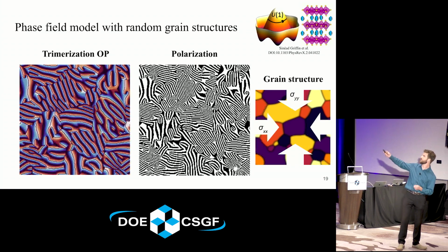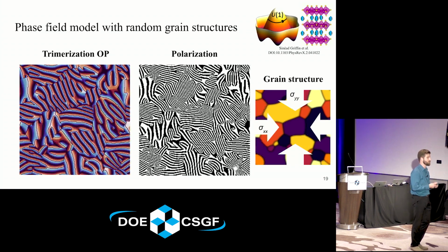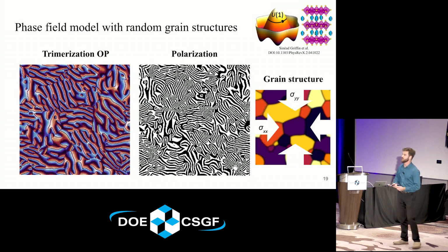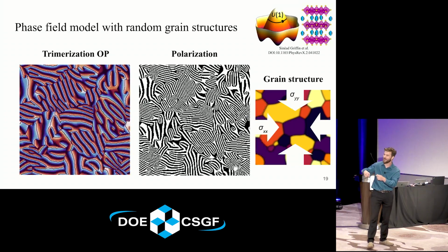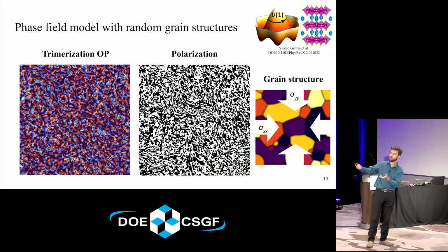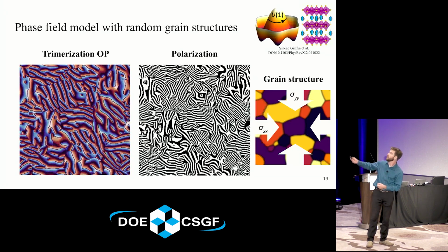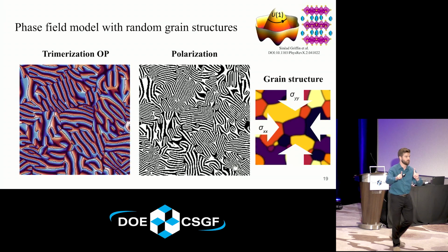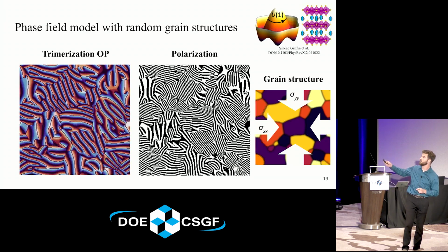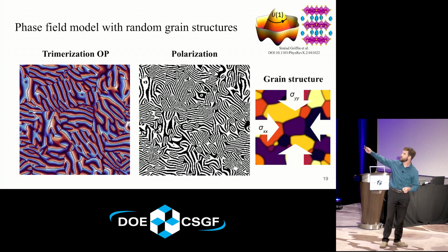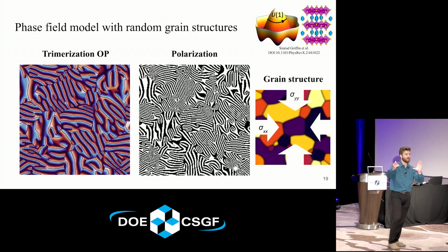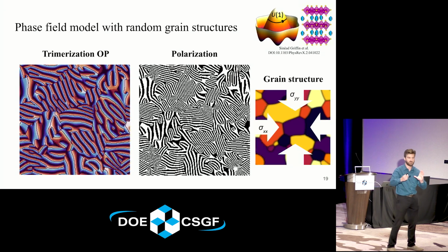So also looking, in collaboration with Sinead Griffin at Lawrence Berkeley National Lab, actually informing from DFT studies that have happened years ago. But again, this is in our custom phase field code, where it's a multiferroic, so you have structural order parameter distortions of polyhedra connected to polarization, as shown in the middle figure. And we incorporate a grain structure and apply a compressive stress to the material.